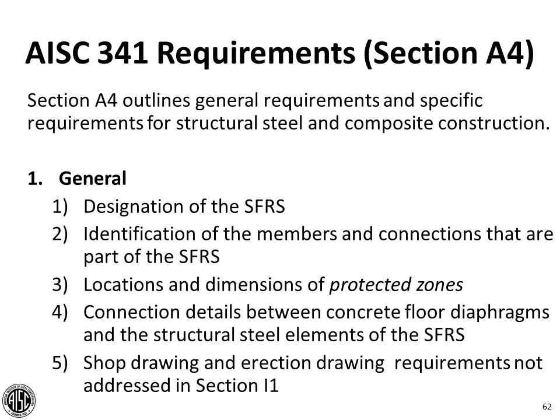The engineer of record is the person in the best position to be able to identify the elements that are in the seismic system. Sometimes it's very easy to see, and as we'll see when we look at frames, for example, it's pretty obvious, okay, those are part of the seismic system. But then how the frames are connected to the balance of the structure, it's not necessarily obvious. And that's some of the information that needs to be shown. Larry also indicated the issues with respect to demand-critical welds and protected zones and things like that.